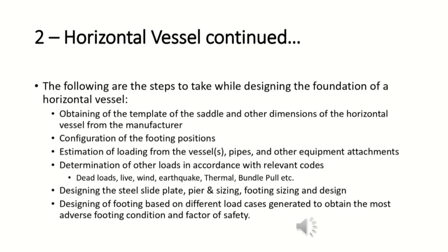6. Designing of the footing based on different load cases generated to obtain the most adverse footing condition and factor of safety. For a horizontal vessel, the number of calculations and load cases to be considered may be large due to the different conditions and the different nature of the supports. So the calculation may be more involved.